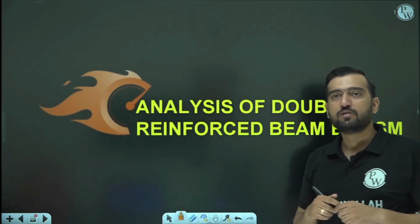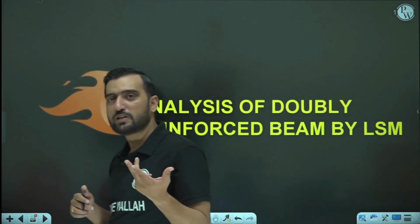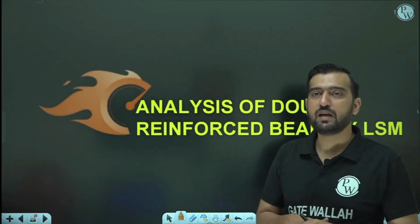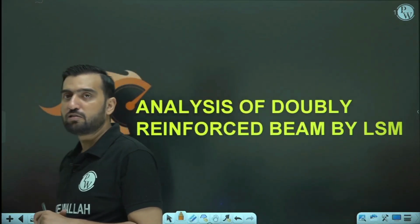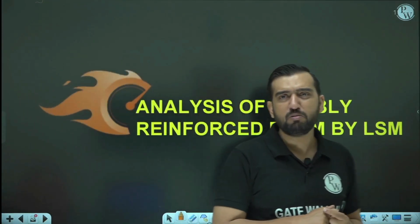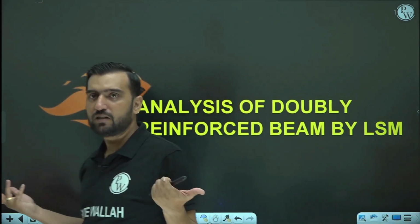So in this manner we can think, in order to increase the moment capacity of a section with the particular grade of steel and concrete and with the fixed size of cross section, we can adopt our doubly reinforced beam. So when steel is also going to come on the compression side, now what is going to happen, my dear friend? The changes will come in step number 2 and in step number 4, because step number 1 was XU lim, that is quite obvious.